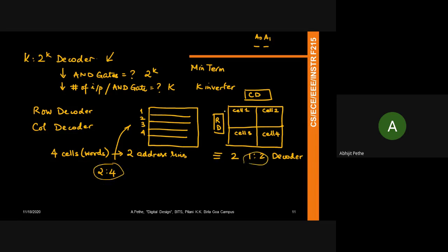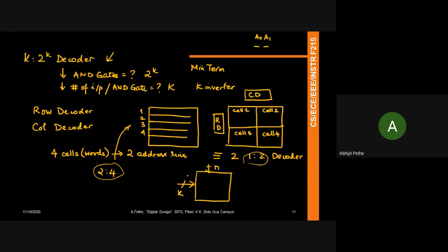So many times when you think about memory, normally today it is not organized just like this. It's normally organized with a row and a column decoder. It might be imperceptible to you if you're sitting outside and this is your block diagram of the memory, where this is K and this is N. You don't care how the memory is organized inside, so you wouldn't know just from the top-level block diagram which way it is organized.